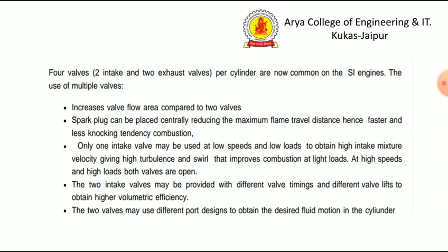Only one intake valve may be used at low speed and at low loads to obtain high intake mixture velocity, giving high turbulence and swirl that improves combustion at light loads and low speeds. At high speeds and high loads, both valves are open. The two intake valves may be provided with different valve timing and different valve lifts to obtain higher volumetric efficiency. The two valves may use different port designs to obtain the desired fluid motion in the cylinder. So these are the uses of multiple valves, which are helpful in reduction of the emissions.